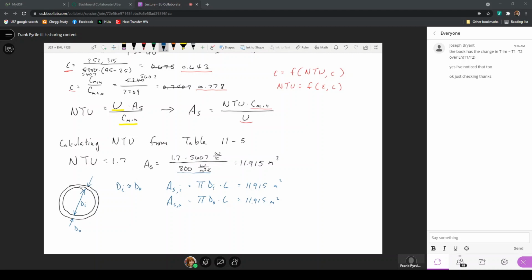And by getting a lower value of the Reynolds number, that means now that I have a different expression for the variation of the heat transfer coefficient through that pipe. That's going to affect what the average heat transfer coefficient would be along the length of the pipe, and thus it would affect the overall average heat transfer coefficient through the heat exchanger. So when making changes to a heat exchanger, because of all of the consequential effects of changing the velocity or changing the fluid or changing the diameter or length of the pipe, these overall heat transfer coefficients